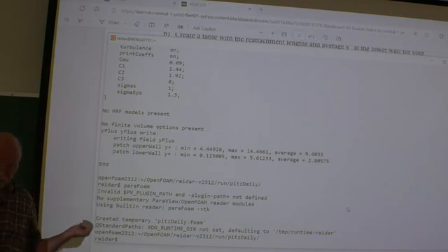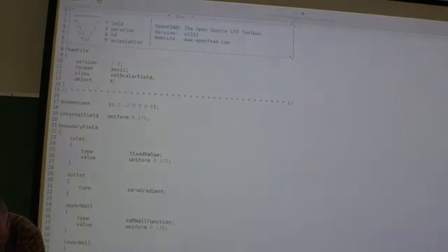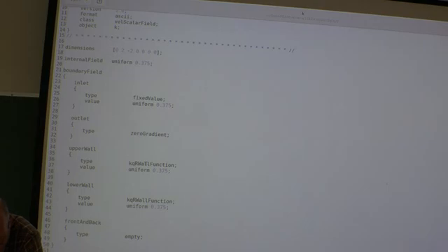So now I have a better mesh, but now with natural boundary conditions. Hence what I should do, I should edit all these 0 files for K, epsilon, and then I should switch this one into a type fixed value, and then a uniform and a very small number.